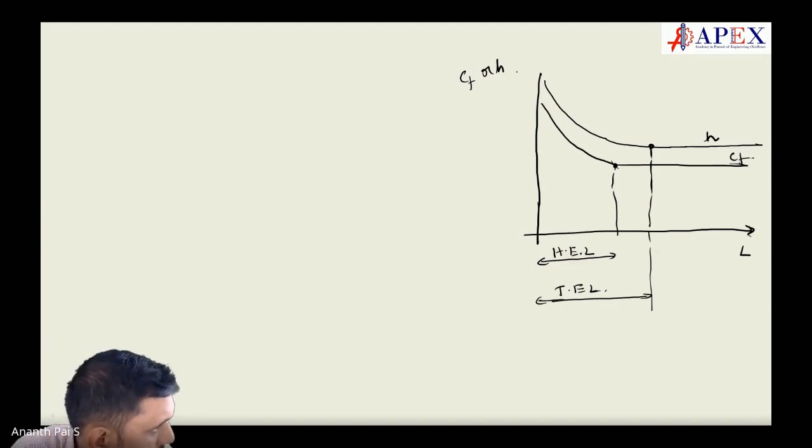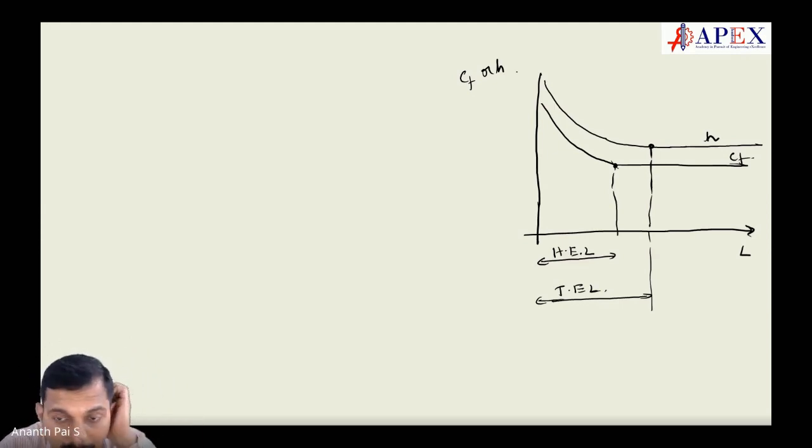Pressure drop is more in the developing region. Pressure drop is constant in the developed region. Pressure drop continuously reduces in the developing region. Heat transfer is more in the developing region. Okay, now the question is, sir, can't we keep only developing regions? We can try.